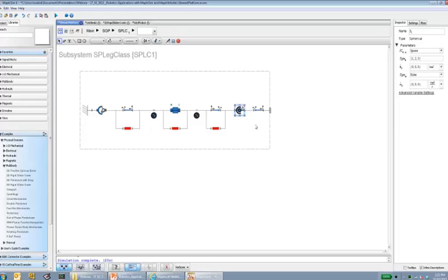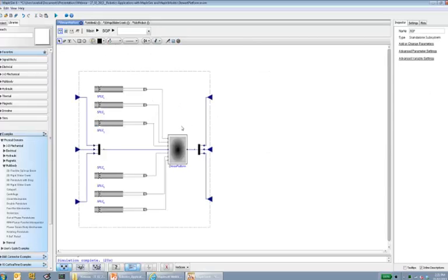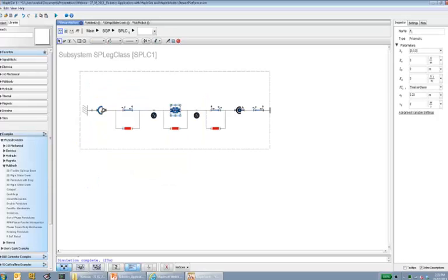The important question that we want to answer, for the inverse kinematic part, is that if we can specify the position of the platform, which becomes the desired position and orientation of the platform, we need to find out what is the extension of each leg, which is the only controlled degree of freedom of a Stewart platform. And that's the inverse kinematic part of this presentation.